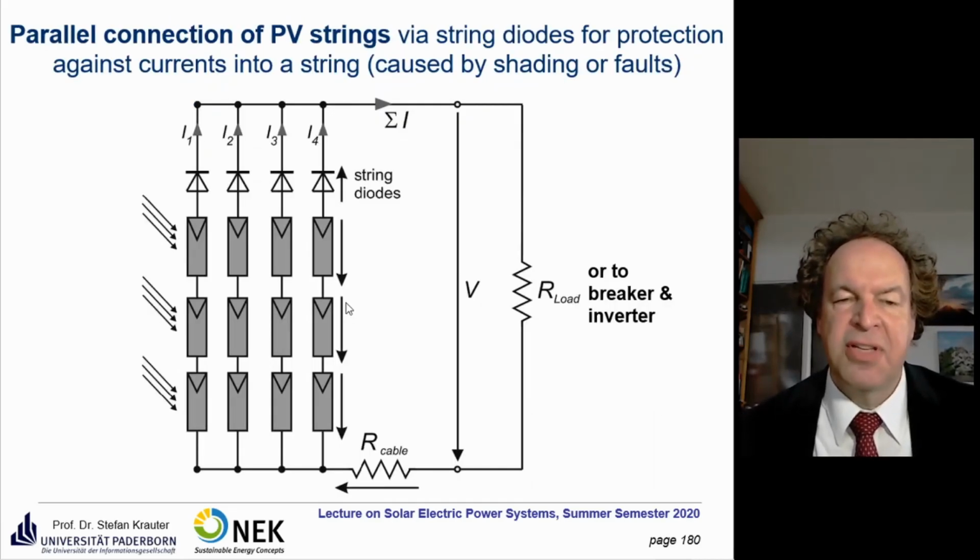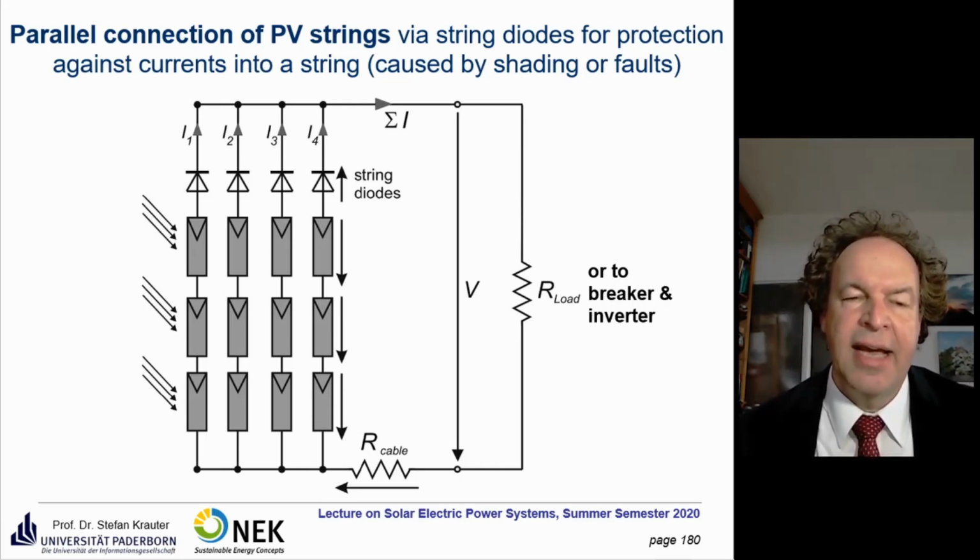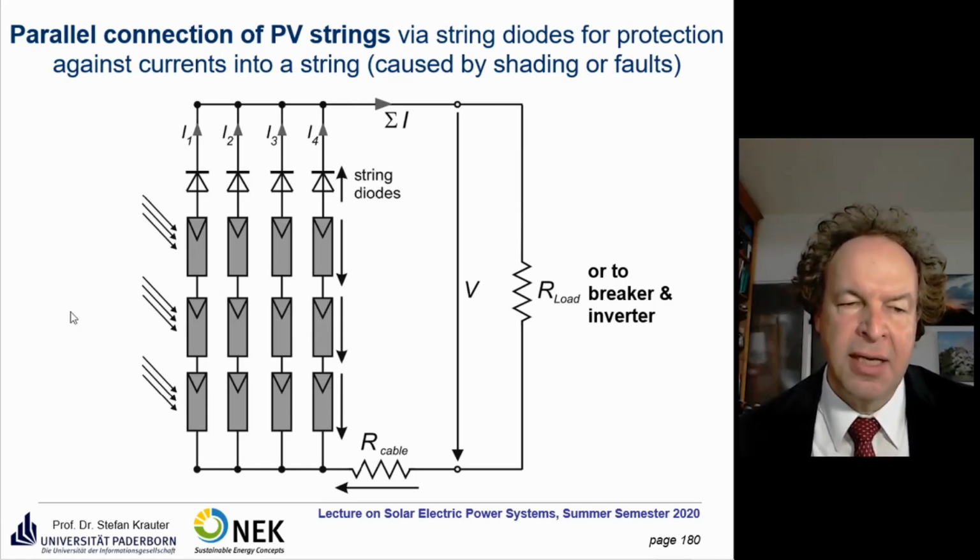Don't mix up with the so-called string diodes. The string diodes are connected in series with a string of solar cells or a string of modules. Usually they don't apply it in cells, but in modules. It is the following idea behind that.